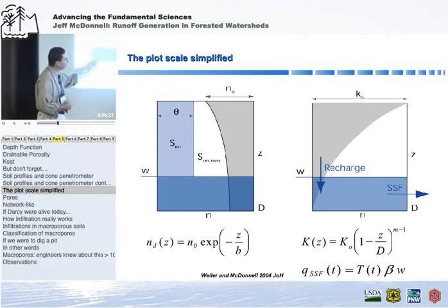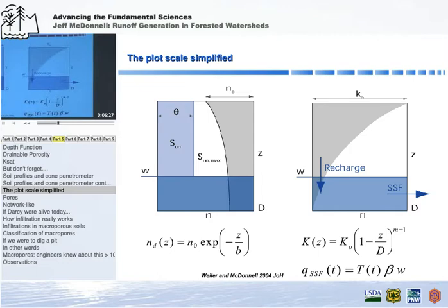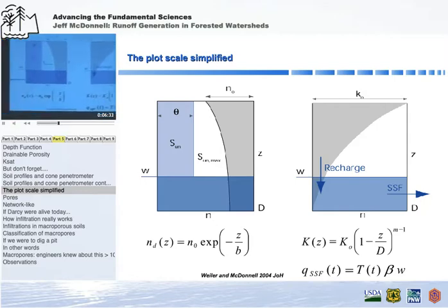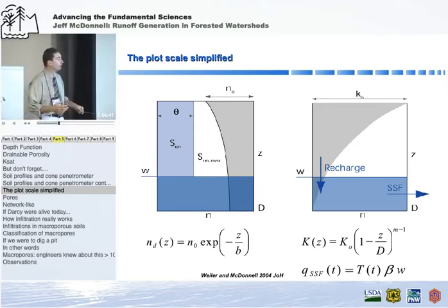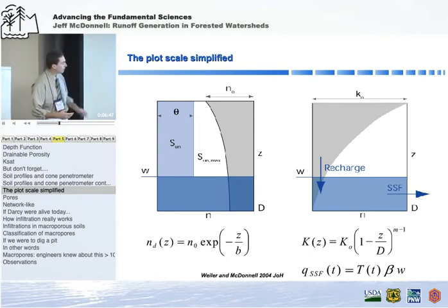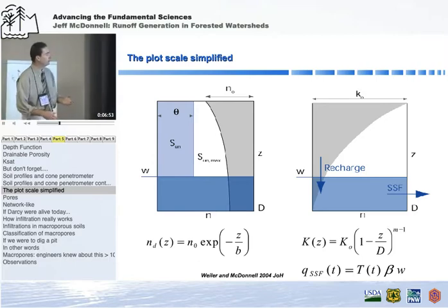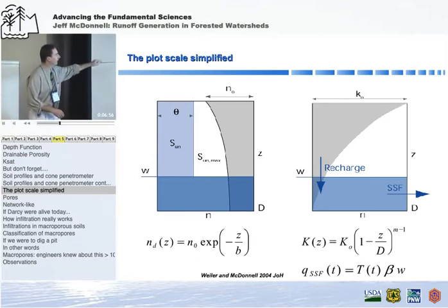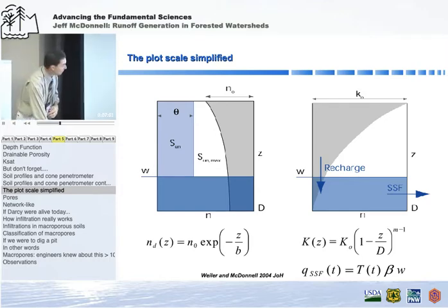And this lateral flow then is really occurring not in the unsaturated zone, even on steep slopes, but in this transient saturated zone. It could be a water table in the till rising into more transmissive mineral soil, saturating this and generating lateral flow, as we'll see as we move to the hill slope scale. Or it could just be water perching at an impermeable horizon, generating saturation, and then the subsurface flow really being a function of these things that we talked about before: beta being the slope angle, W being the depth of water, or the height of the water table, and T being the transmissivity.